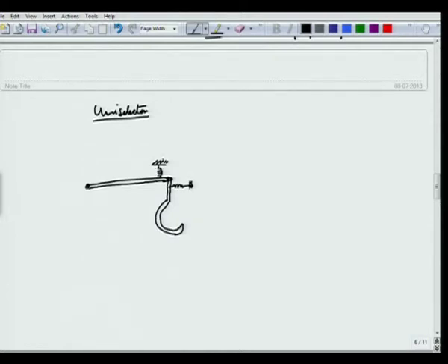So it is always trying to pull this thing upward, and this is being pulled towards this side, okay. And then there is an electromagnet which is here, and whenever you supply current to this, this will come down and then it will go up once the pulse is over. So with every pulse there is a motion of this particular bar coming down and going back up.